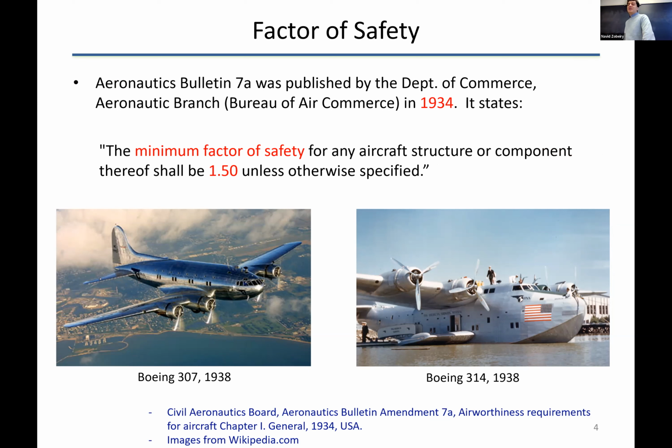For factor of safety, two things are important. Below limit loads, you don't want to have any permanent deformation. With an aircraft flying, you don't want permanent damage all the time, so you want to design it such that it would never experience permanent deformation. And then beyond that, it should never fail. So think about that permanent deformation. Where do you think 1.5 comes from?